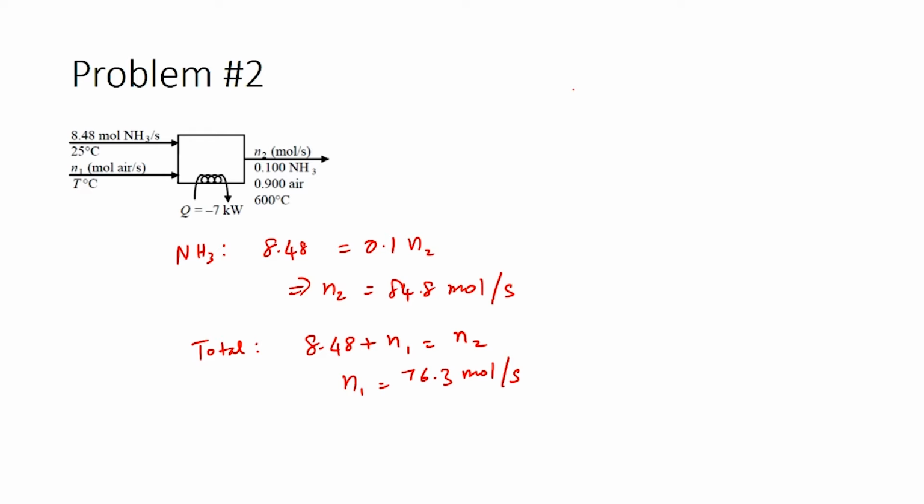So, we have the energy balance equation as Q dot minus Ws dot equals delta H dot plus delta Ek dot plus delta Ep dot. Ek and Ep go to 0 because there is no change in kinetic and potential energies. There are no moving parts, so Ws goes to 0. So, Q dot equals delta H dot is the energy balance equation we end up with.